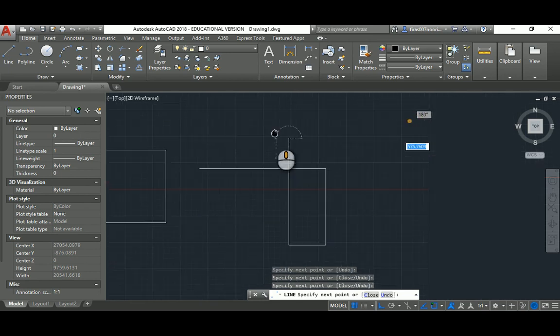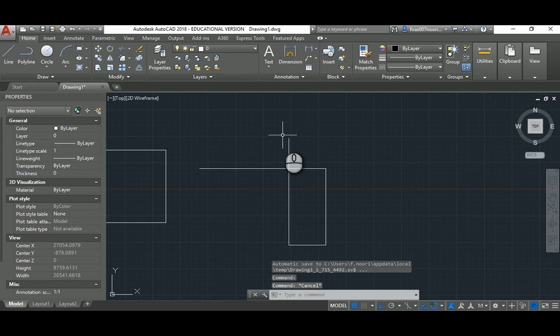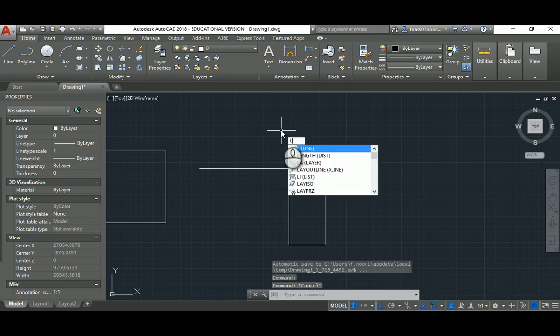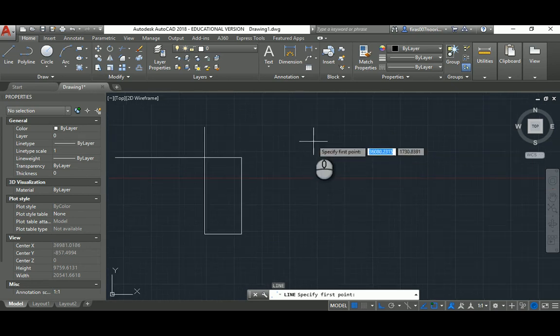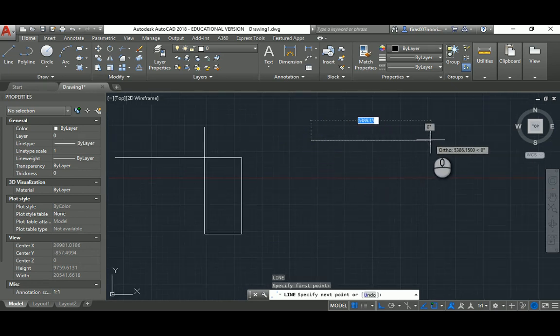Now if I want to use more specific units in the drawing process, I can go L space or L enter. I'll put the first click, move my hand to the right, and you can immediately see with Ortho it's telling me it's locked on 0. Even if I push it a little bit up or down, it's locked on 0. While the bluish text, you see, is going to ask me to give the number.